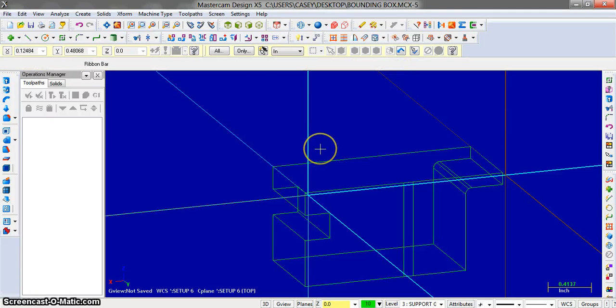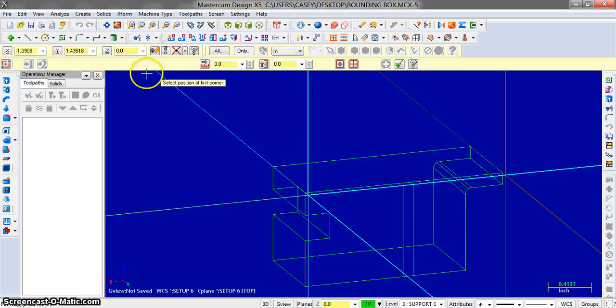Click OK. And now we're going to make the L, which goes about like that. So I'm going to click there and make the dimensions, which is going to be length is 0.25, and your height's going to be 0.094. Accidentally typed a 3, that's okay. Click OK after doing so.